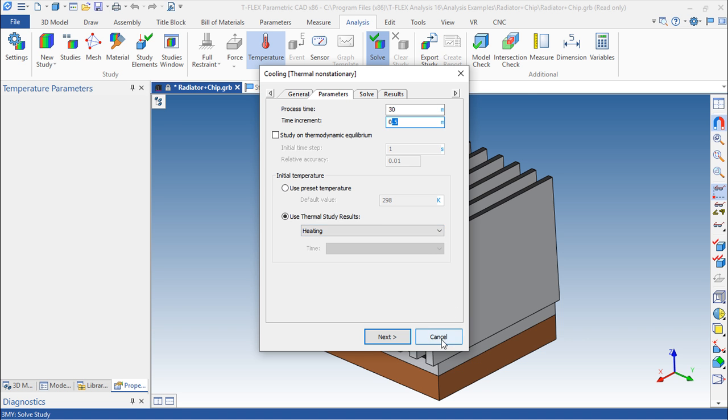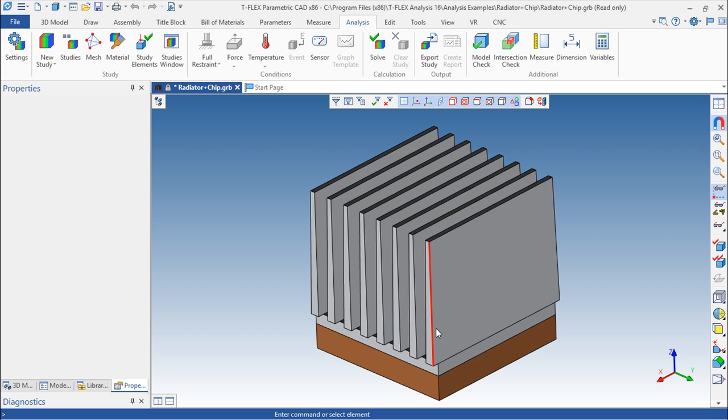Finally, the results that we may have from this study are temperature fields, which you can define as a temperature distribution over the model's volume. Thermal gradients by the three axes, x, y, and z, and the magnitude of those thermal gradients. These, what we call the thermal gradients, reflect the degree of temperature changes by each one of the axes of the coordinate system.